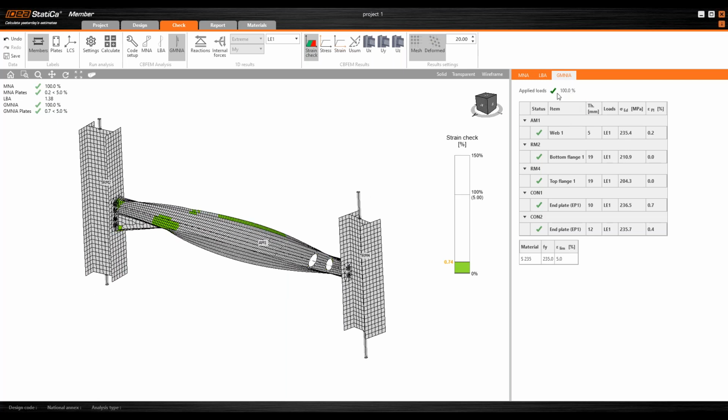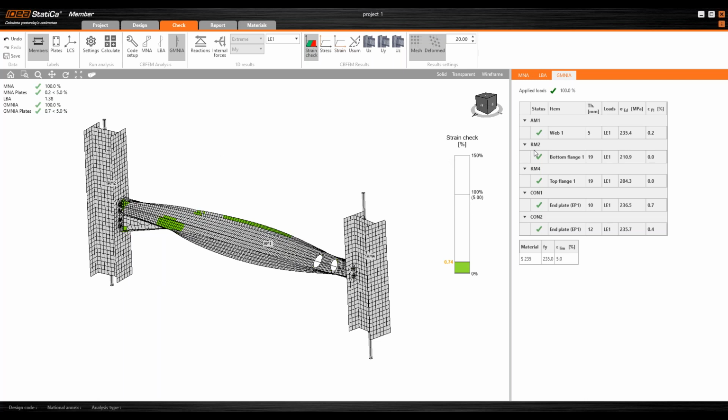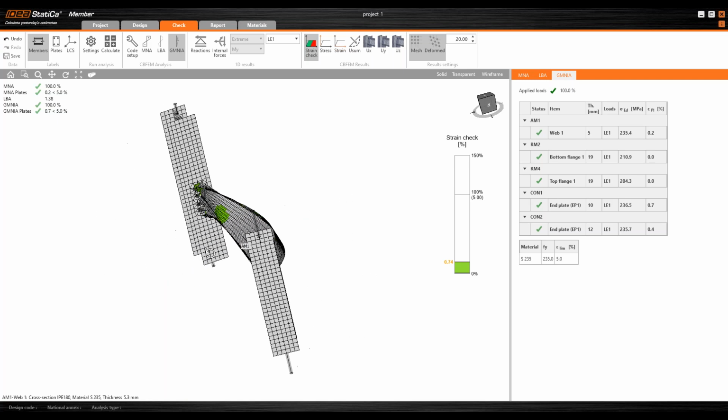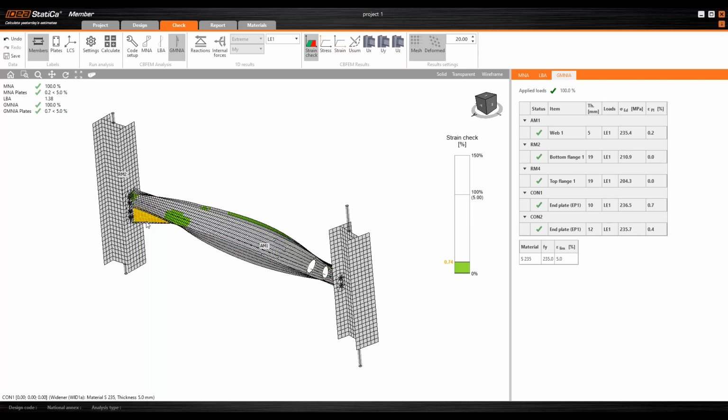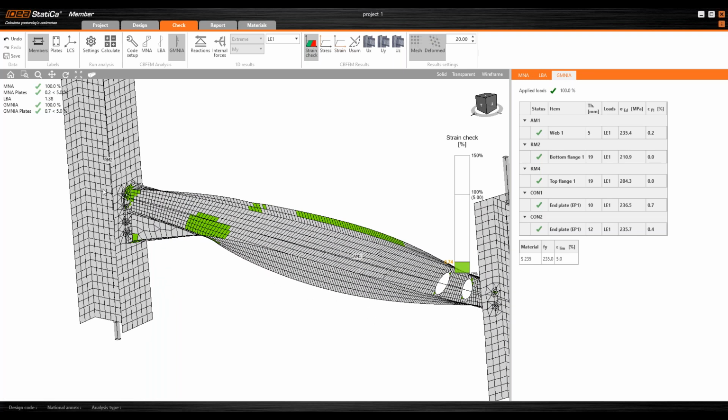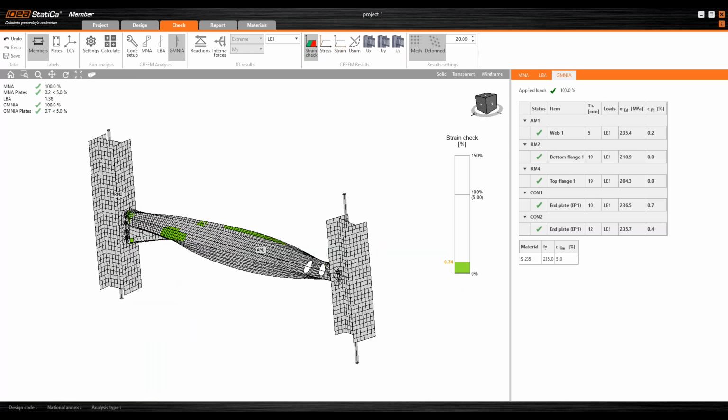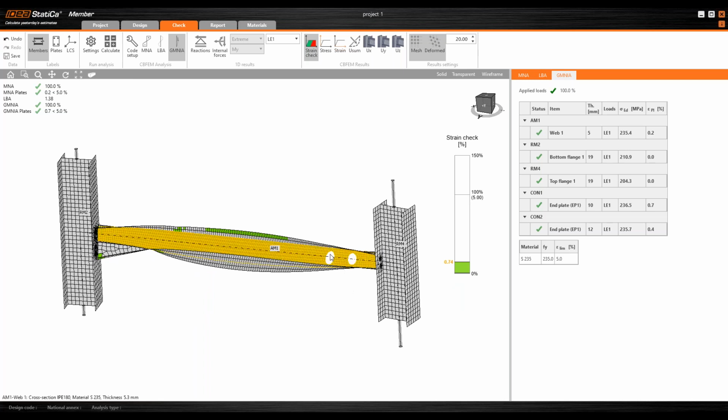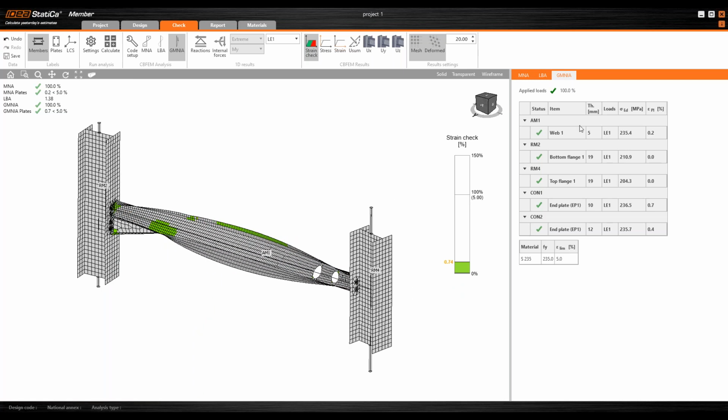Because I see now the applied 100% of the loads, so these 20 and this 500, and I can see that I pass the checks, including imperfections, including the possible stability losses, including, of course, the exact rigidities, stiffness values of these connections, of these supports, position of loads, openings, everything there, all calculated, analyzed, and put against the code checks.